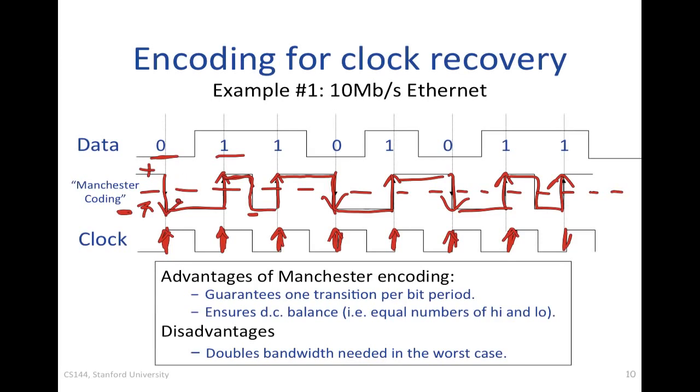And so I'm making sure that I get DC balance in the long term. The benefit of this is that in order to correctly differentiate a 1 and a 0 at the other end, I just need to set my threshold to be in the middle, or the average, on the wire. So that makes for a very reliable and robust recovery of bits at the far end.